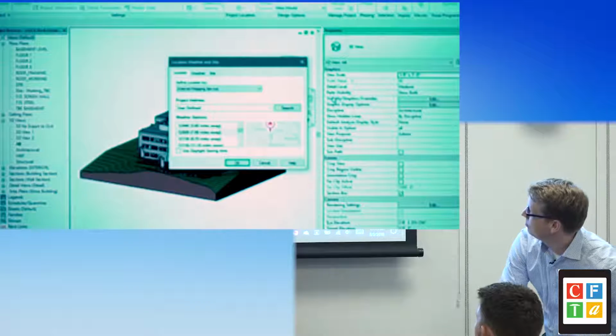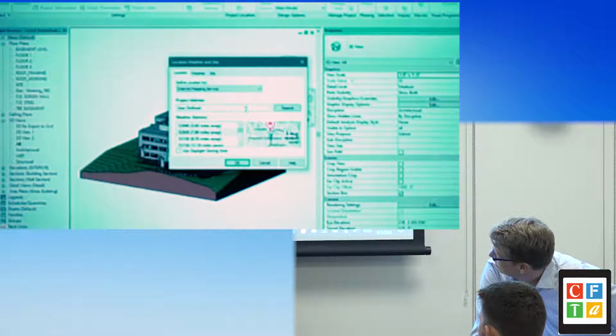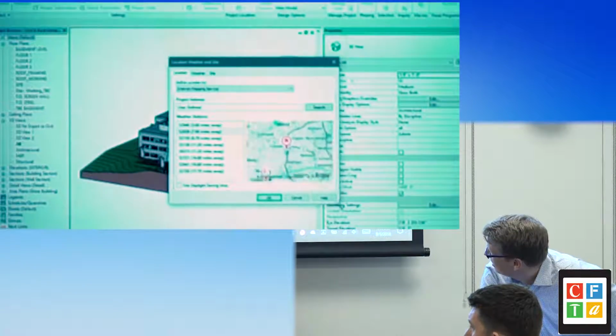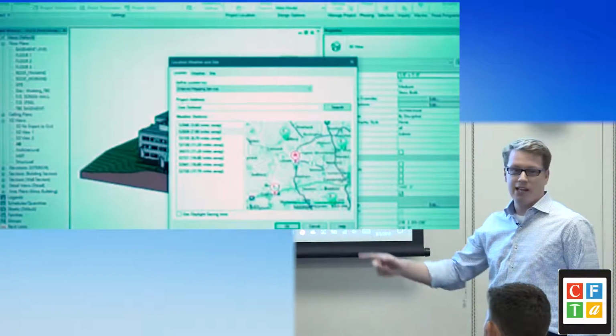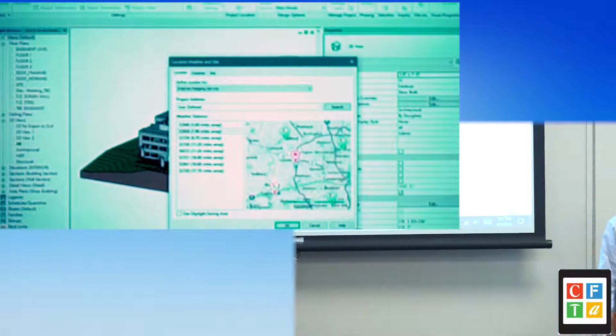One of the first checks we do with architects is to see where the building is, because a lot of them hadn't been used to that process. If it defaults to Waltham, Mass, which is the default in the software, that means they didn't move the building to where it's supposed to be. Unless, of course, they're using this building, which is in Waltham, Mass, and is geolocated for that.